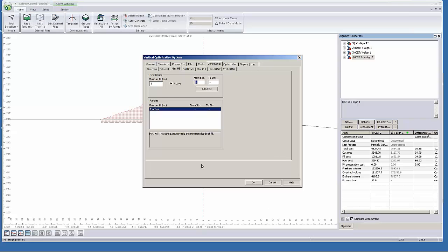It's also possible to over-constrain a problem, to give it constraints that are impossible. I want to go through these control points, and I want to have this K value, and I want these grades, and you've got too many control points, and you go to optimize it, and it says no solution found. It's infeasible. It's simply geometrically impossible to do what you've asked. You can't. So it helps you determine situations that are infeasible.